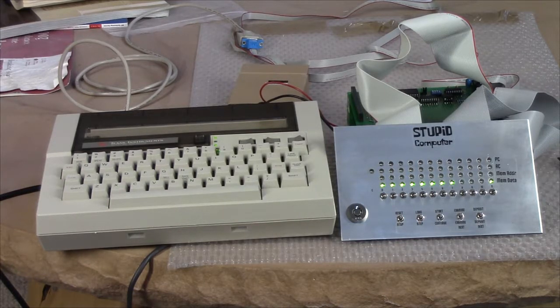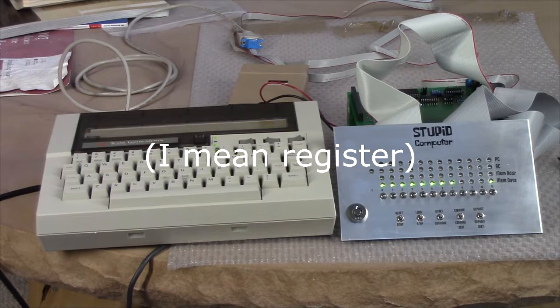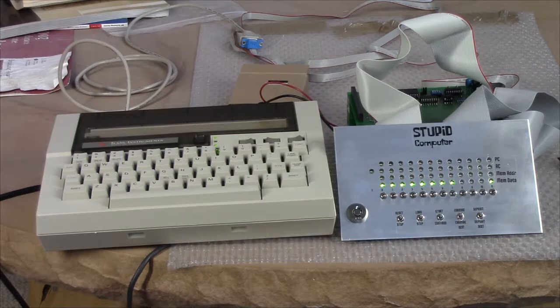So if you read and write in the same instruction and you have a feedback loop, say you want to increment an indirect register, you would read from that indirect register, pass it through the ALU, increment it, and pass it back in to the same register address. Well, that just passes right through and it loops around again and again and again. And so it increments by much more than one.